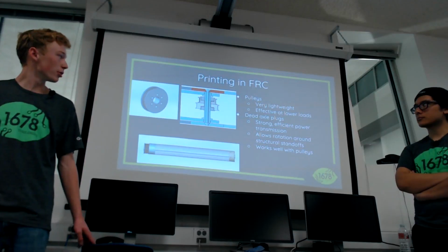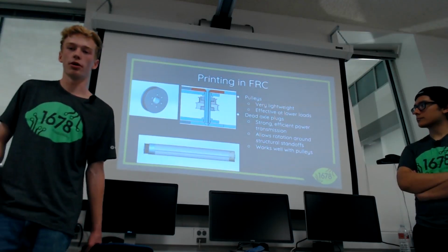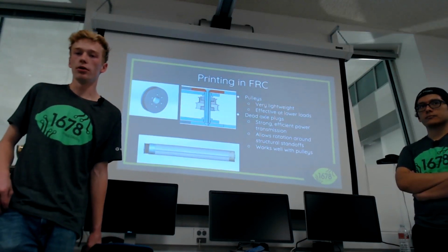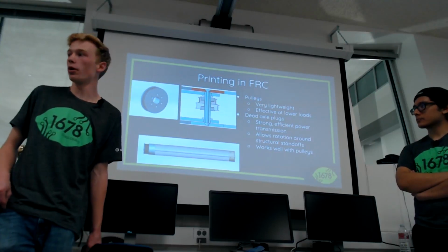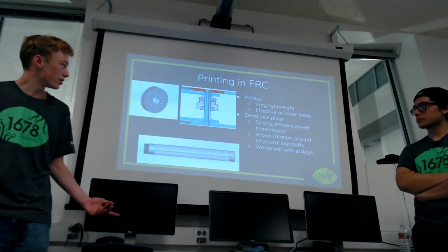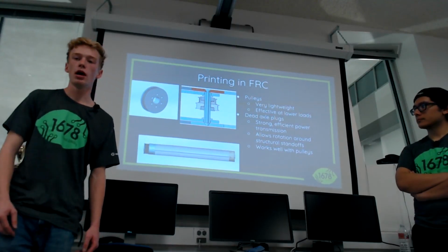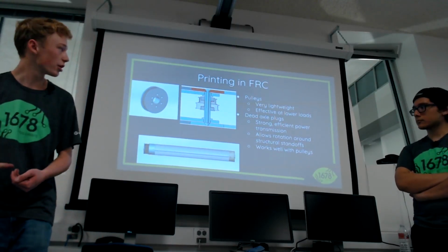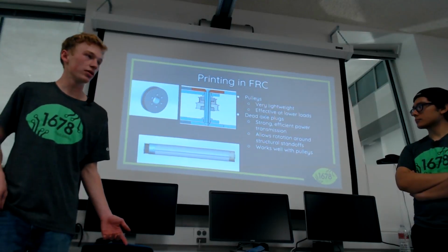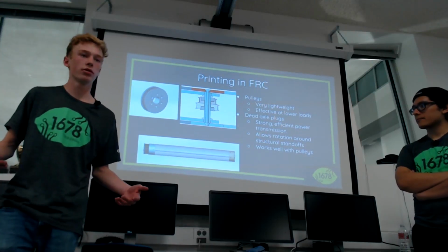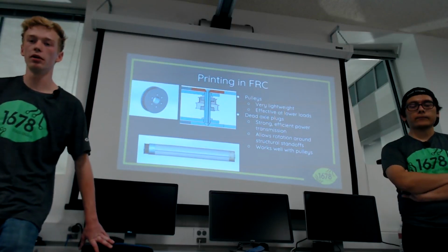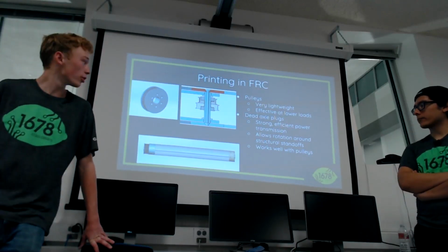And kind of similar, I think dead axle plugs are a great place for 3D printing too. For those of you who are unfamiliar with what a dead axle is, the idea is, just as it sounds, you have a stationary axle going through the middle of some moving components, and then parts that are rotating around that stationary axle. They can be as simple as a pulley with some bearings in it, or they can be pretty complicated. And they have several advantages over live axles.